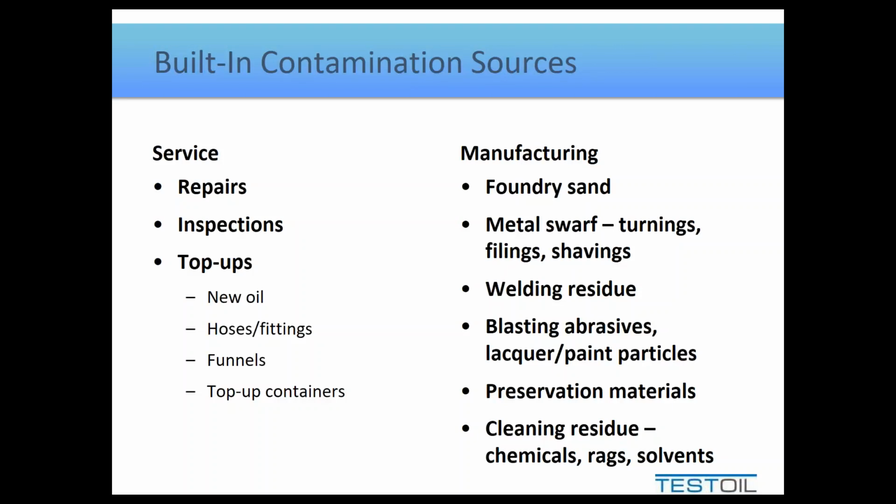So the aluminum block engines, the way they're created is by sand casting. And as it turned out, some of the engine blocks were not being thoroughly cleaned as they were being assembled. So there was actually leftover foundry sand inside the engine. And it didn't do anything until they filled it with a lubricant, and the lubricant was able to circulate it to some of the other moving parts. And at that point, it caused the premature wear.